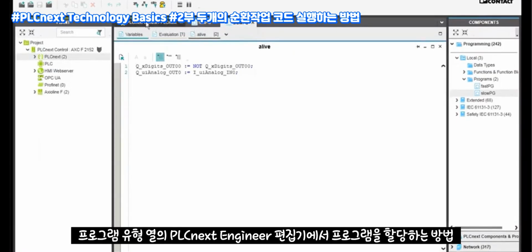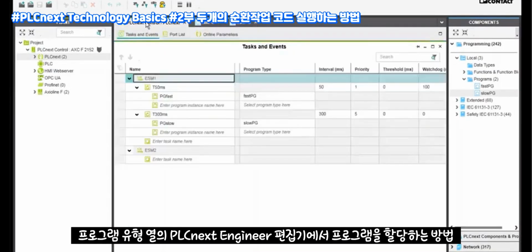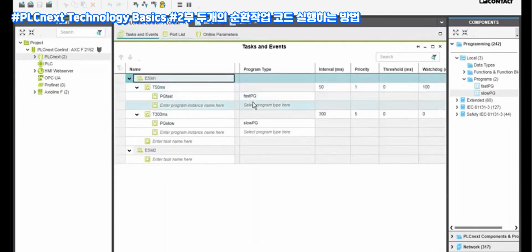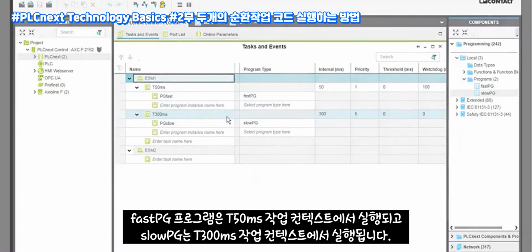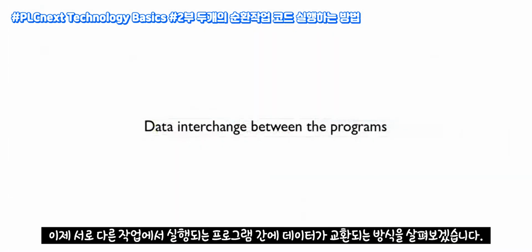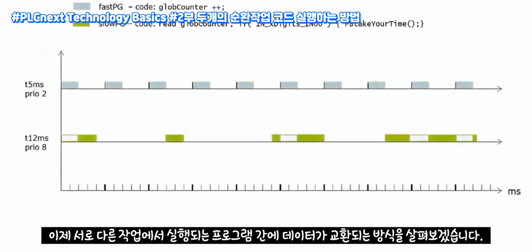How the programs are assigned to the tasks, we see in the PLCnext Engineer editor in the Program Type column. The FastPG program is executed in the context of the T50 milliseconds task and the SlowPG in the context of the T300 milliseconds task. Now let's see how the data is exchanged between programs that are executed in different tasks.